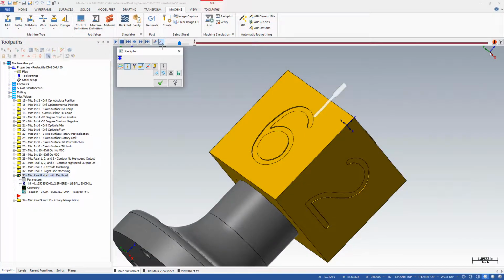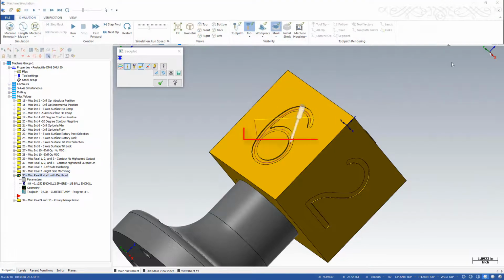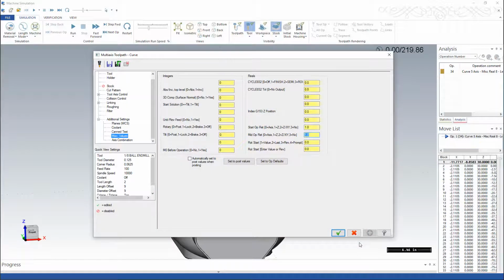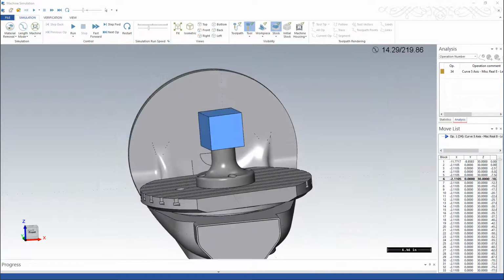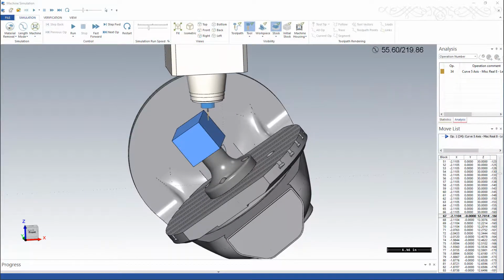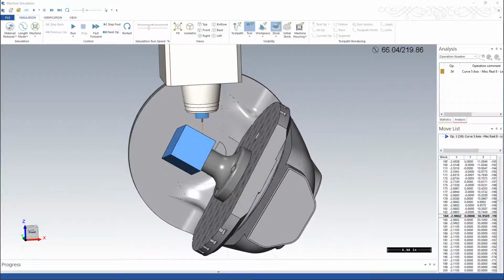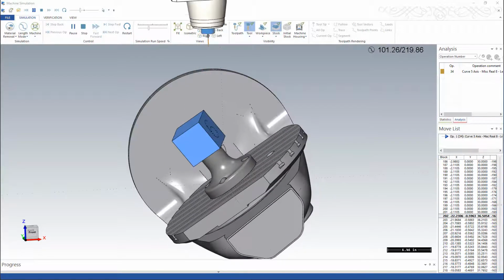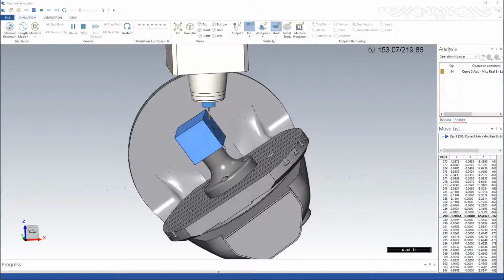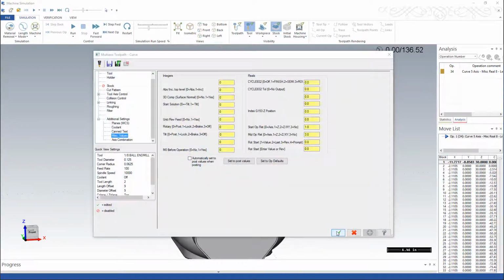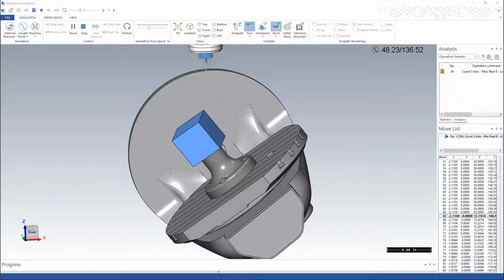These examples have shown cases where use of a retract before an index is preferred. It is likely that some situations would be more efficient without a retract. For example, if op 33 was only cutting one chain but was taking multiple depth cuts, using the default value of 1 for real 8 would result in retracts between each step down. Setting this to 3 to cancel the retracts would result in a much more efficient toolpath.